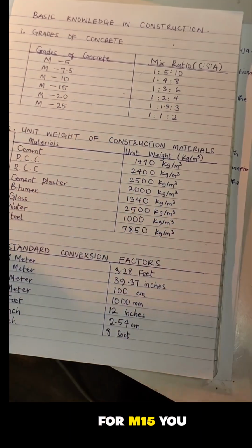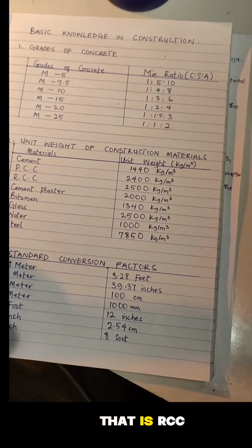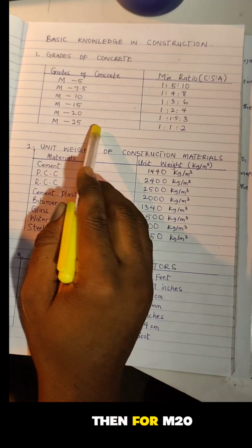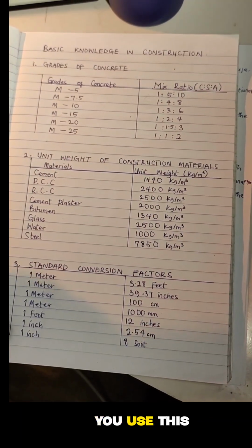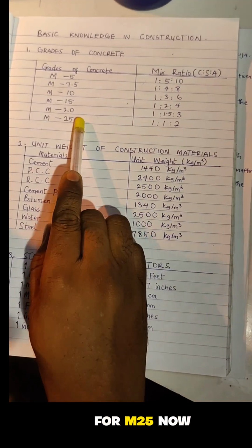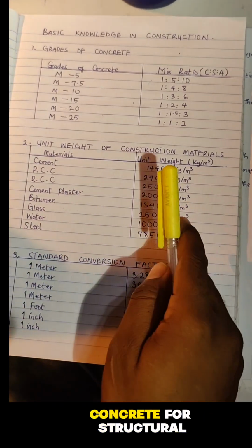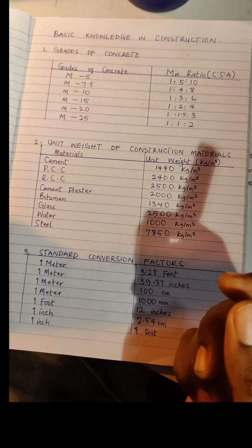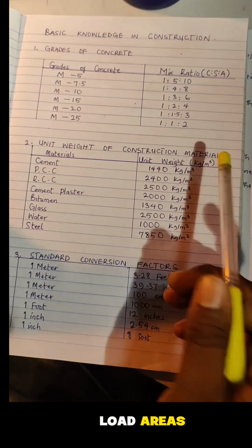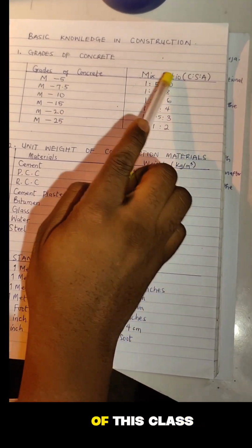For M15, you use it when you have a simple reinforced concrete, that is RCC, like slabs and small structures. Then for M20, you use it for standard concrete grades for beams, slabs, and columns. For M25, which is the highest grade we have here, we use it mostly for strong structural reinforced concrete like footings, columns, and high load areas. Okay, then this mix ratio is for the purpose of this class.